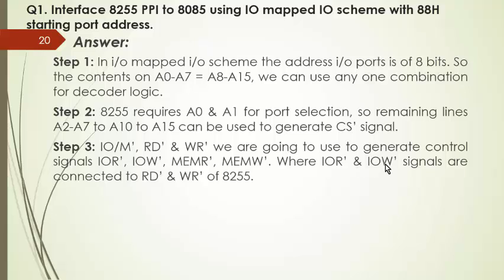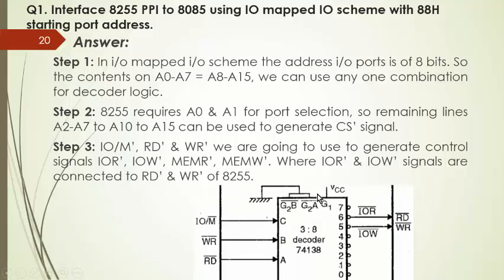The IO read bar and IO write bar signals from the decoder are connected to read bar and write bar of the 8255 IC.